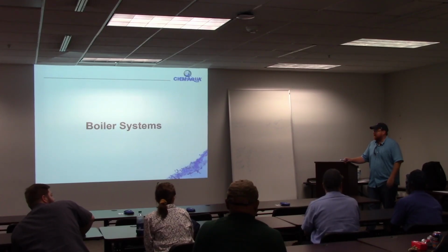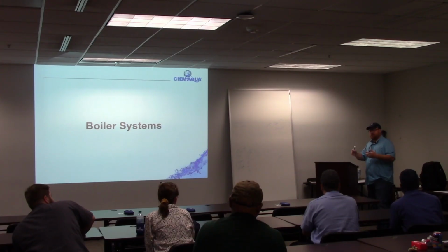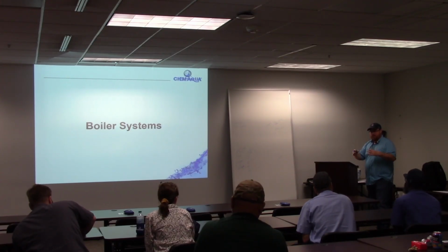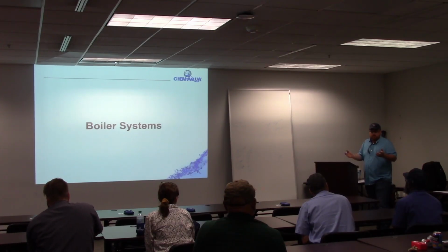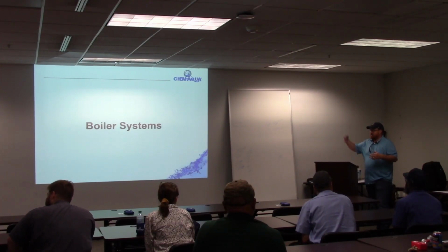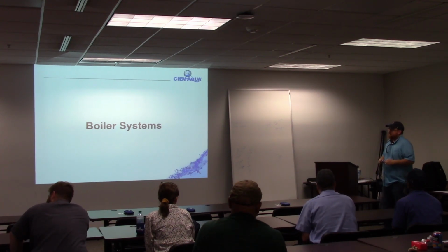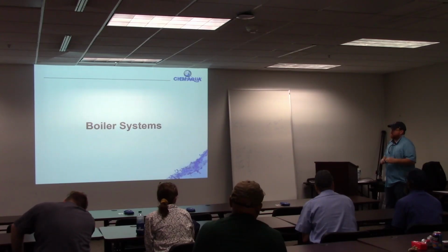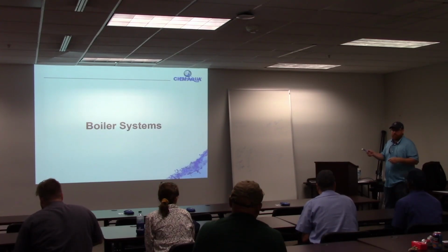Boilers is kind of the same concept, really. In a cooling tower, you're evaporating water, right? And you're concentrating minerals because you're evaporating water. In a boiler system, you're making steam, if it's a steam boiler, and because of that water loss to steam, you're concentrating minerals. The main difference between the two is there's an inverse relationship between temperature and solubility of minerals. So in a boiler, you have high pressure, high temperature, so you can't have as much dissolved mineral content as you can in a cooling tower.